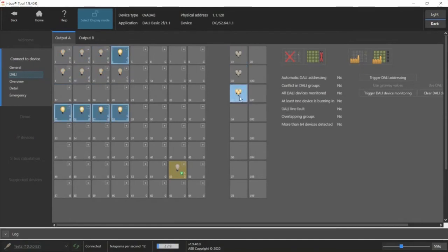So as I said very much earlier on, DALI gives you the flexibility in an office. You know, partition walls go up, partition walls go down, all that sort of stuff. Just by logging onto the system here, you can quickly change and readdress all the DALI ballasts. Once you've done that, bingo, you've no rewiring to do. You can just allocate them to different groups. And then you've changed your fitting, you've changed your network, everything's sorted. There's never any problem with it. So that's just the simple side of this, how we can work. It's really quite a handy tool.